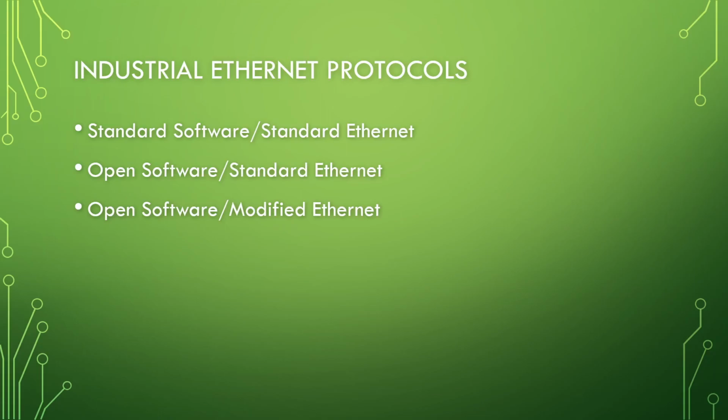And this adds mechanisms built into the application layer to enable real-time communication. Remember, we were talking about industrial networks sometimes needing sub-5-millisecond response time. If we need real time and we're relying on Ethernet, it's not necessarily going to be real time. Maybe you guys have been running a ping test. Sometimes it doesn't go very quickly. So that's something we need to be aware of.